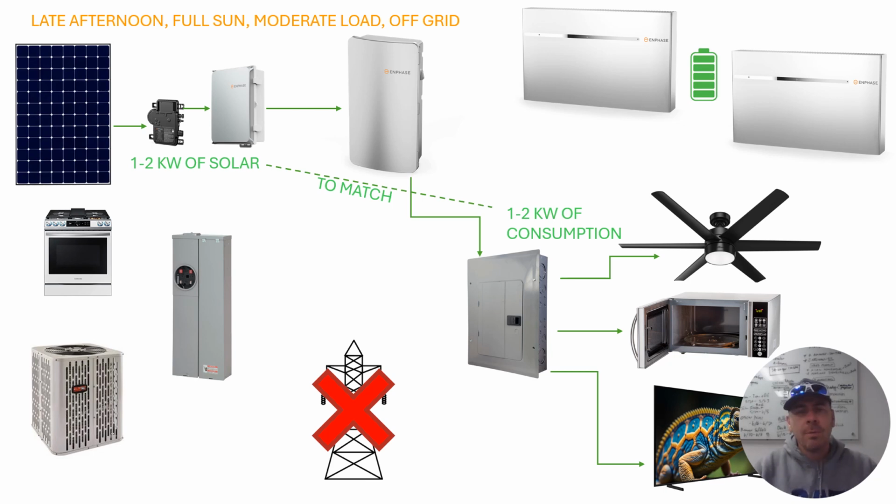The system starts controlling and managing how much solar is being produced. And it's able to do that whether it's the microinverters or whether it's an all-in-one system like the NeoVolta, and it modulates and controls how much solar is going to be produced. Or it can just turn the solar off and cycle batteries off and on, and then turn the solar back on to recharge the batteries. And then what the system does is it automatically self-regulates, self-modulates everything, and controls how the solar and the battery are working together to make sure that you're getting the power delivered that's needed for your backup loads,